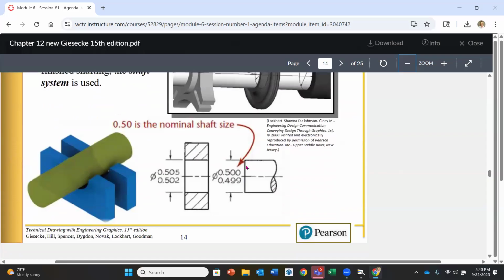We've got a nominal size on the shaft. This happens when we have a specialized type of shafting that might be ground and hardened to a certain size. And a lot of times that nominal is going to be in there. So that means I'm purchasing specific special material, and then I'm going to have to put the allowance on the hole size.